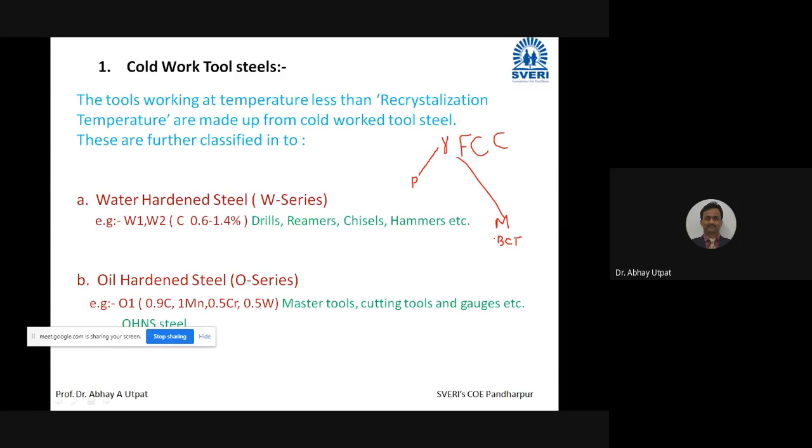So why is this happening? Because of a large delta T. You are at 900 degrees Celsius and water is at 20 degrees Celsius. 900 minus 20 will be delta T. This much, 880 degrees Celsius temperature drop, in 2-3 seconds. Because of that, there will be crack generation and stress in the component. If you want to avoid this stress, because your mechanical components are completely manufactured and formed, and heat treatment is the end process, you should not lose the shape or get cracking in the component.